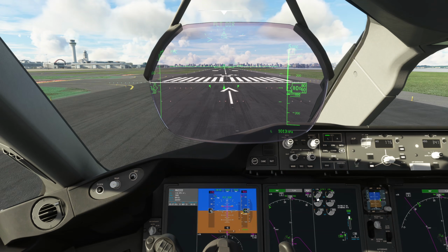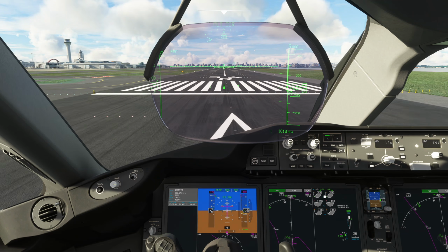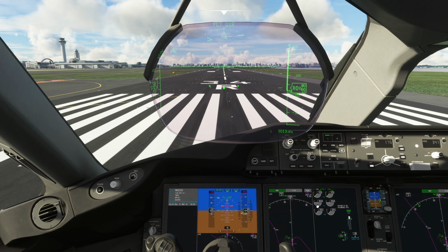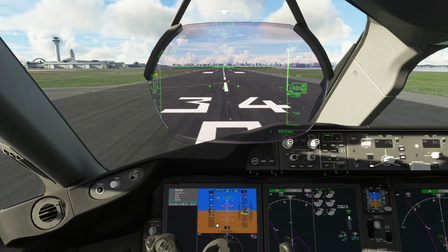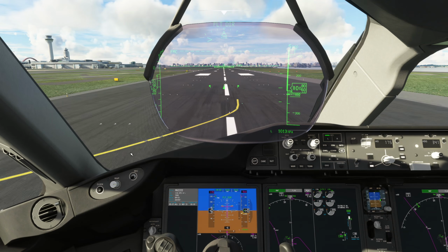We just need it there by 80 knots. So remember, we're looking for 71.6, which you'll notice is only 84%, but there we go. So that is thrust set, and you can see we are quite heavy.